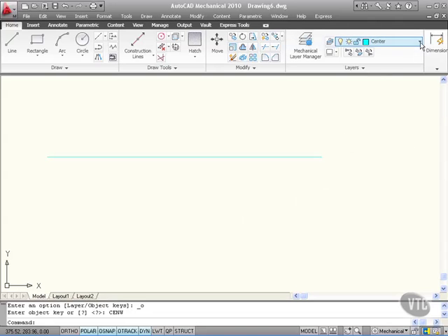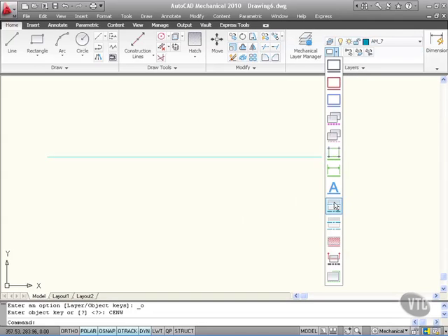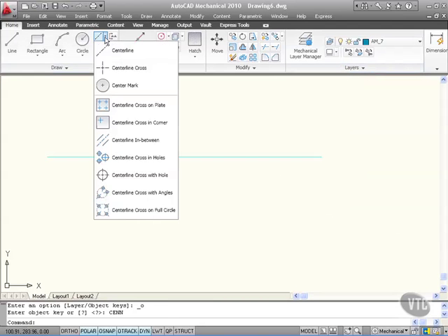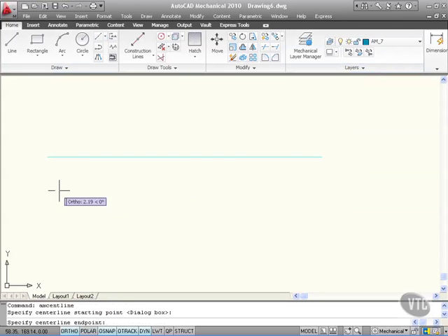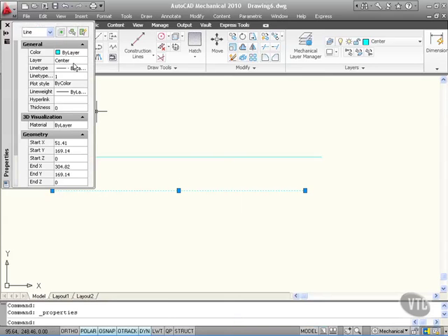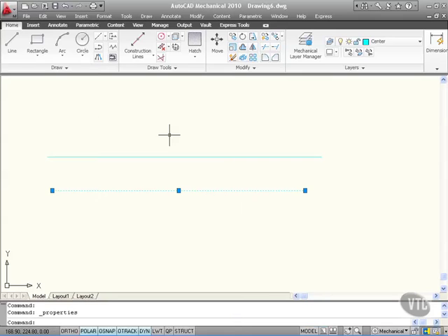So what I've got to do there is I've actually got to go to AM7 here, and then if I click here, let's try another center line and see what happens. There's the AM7, but look, if I go and draw a center line again, it defaults back to my center layer. You can see the color is the same. If I go back to Object Properties, you can see it's still using that center layer, like so. So let's close the Properties palette there, and let's hit Escape.